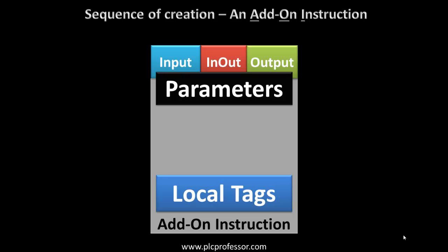Do you remember what sets these parameter designations apart? That's correct. Some are by reference, referring to a tag in the general tag population, or by value. And last but not least, the code, which is the entire purpose of the add-on instruction.